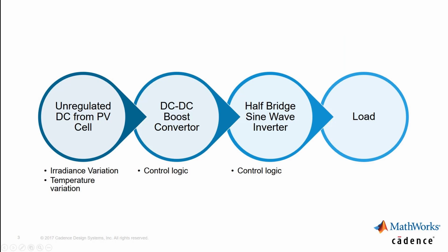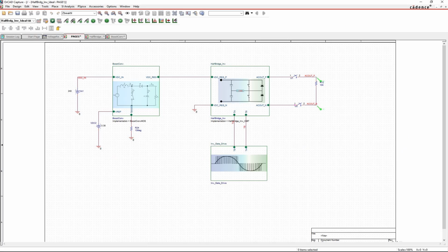There are various building blocks of the system. We'll start our design with OrCAD Capture for circuit design, and as you can see, we could replicate the exact architecture here as is. This improves the traceability and debuggability of the design. OrCAD Capture enables you to capture your simulation design in a flat or hierarchical manner. By using hierarchical design, we can design and optimize individual blocks independently and connect them together. So this is kind of a bottom-up design approach. This also enables team design and concurrent design, where teams are working on respective modules in parallel.